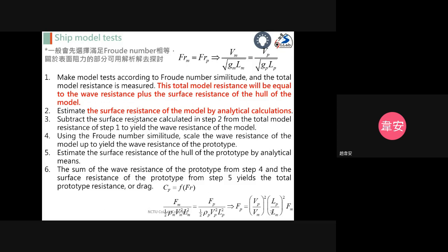This slide summarizes how we deal with ship model testing. I would like to emphasize you need to consider the Froude number first, and we can estimate the resistance related to the viscosity effect by modeling or direct computations.